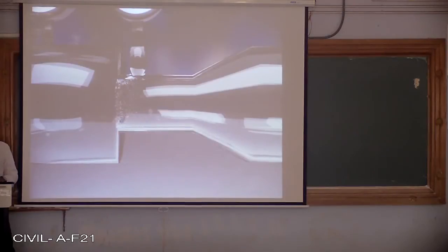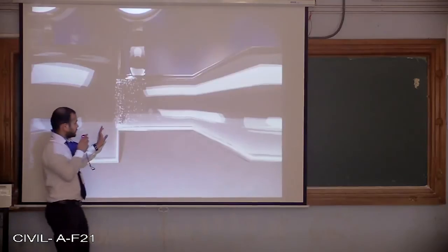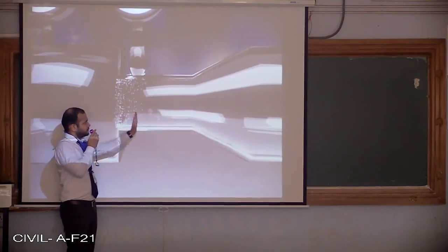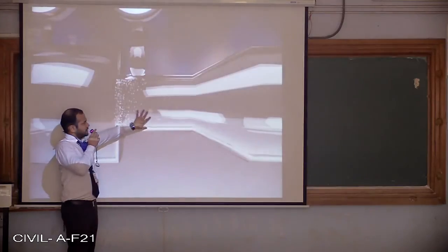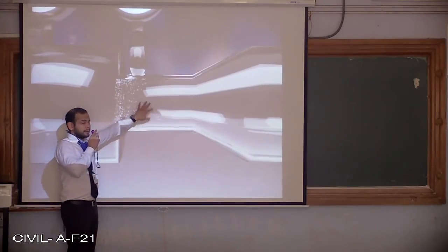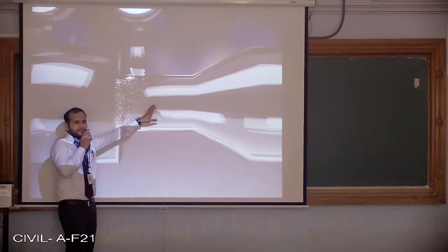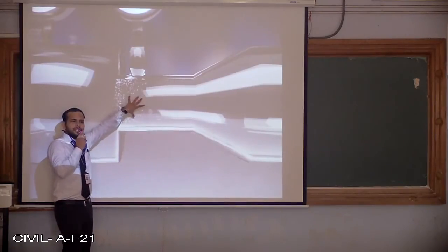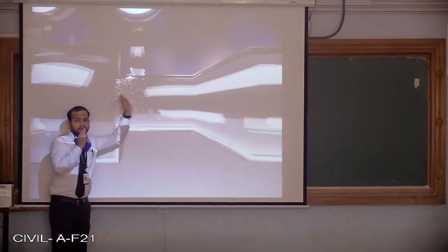Because water from the vapor bubble occupies... You can see from here the water vaporizes, forms bubbles, and as soon as the pressure is increased above the vapor pressure, it will again become normal and burst. So this is the critical cross section inside a pipe. Here we need to be very careful.